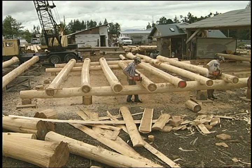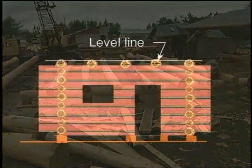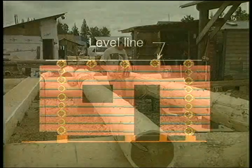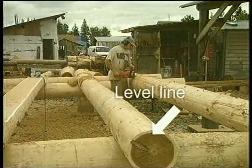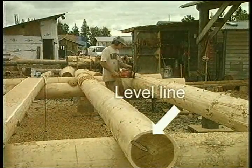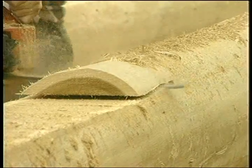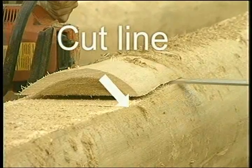Here the end logs have been reset on the ground for convenience. When all the joists are in place, you can snap a line across the ends. The line should be equal distant from the foundation at all points. Again, it is best to remove the log from the wall to do the cutting. If removal is out of the question, you might build a scaffold and roll the joist to that spot.